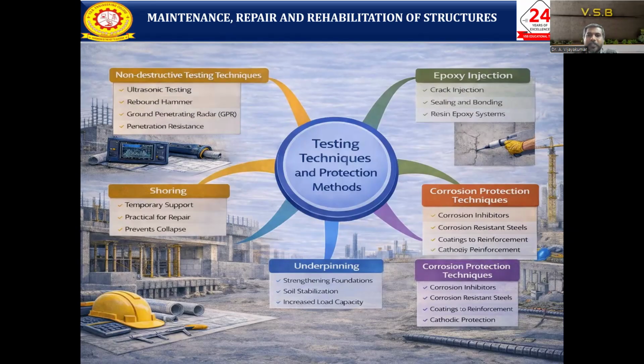Then we discussed epoxy injection, crack injection, sealing or bonding with an epoxy resin system, with which we can repair cracks. Shoring is temporary support during repair to prevent collapse. Underpinning is used for strengthening the foundation, where the soil is weak, to increase load carrying capacity.